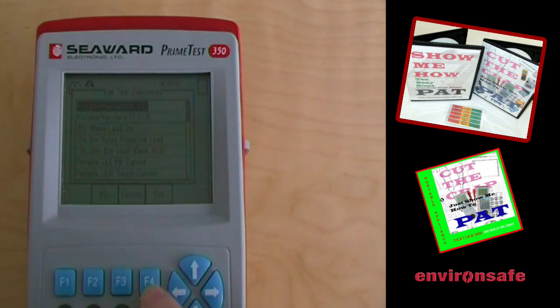To find out what the sequences are, we need to go into the edit menu and press F4. So we're going to the portable handheld IT class 1 to see what the sequences are. And the sequences are, using the down arrow, visual test, earth continuity at 5 seconds, limit 0.10, the insulation at 500 volts, and the end of the test.